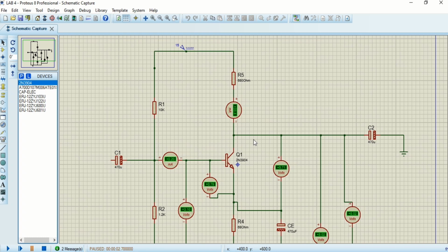Alright, following the table that I recorded and put in the lab sheet. This is for the IC, which I got as 33.8 milliampere. This one is 0.2 milliampere for IB. This is for the VBE value, and I got 0.79 volt. And this is for the VB value, and we got 3.1 volt.